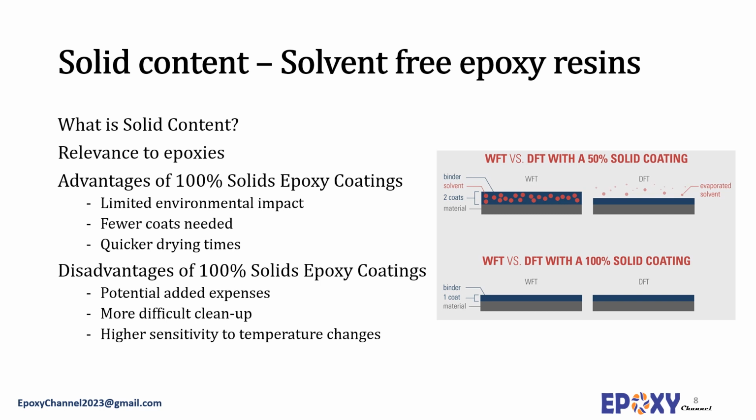Solid contents. It refers to the amount of base product proportion of non-volatile material left in the adhesives once the volatile solvent has vaporized. This number is expressed as a percentage. Solid content describes the part of liquid that will become solid after it has been applied and had the proper time for hardening.